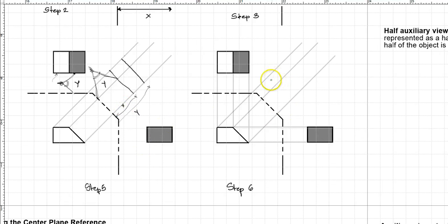And we just transfer it right there. So when I'm looking at the object with this line of sight, this is what I see. So now if you look, I see two surfaces, there and there, which is that and this. So I have to darken this edge.